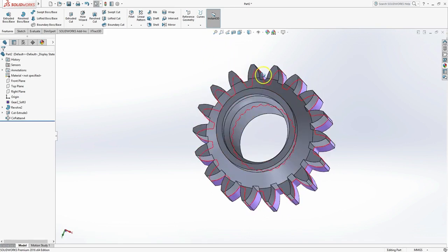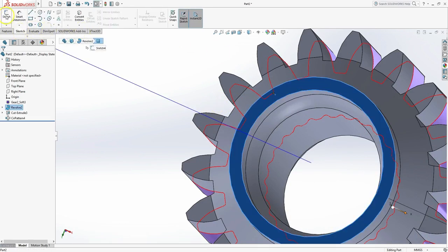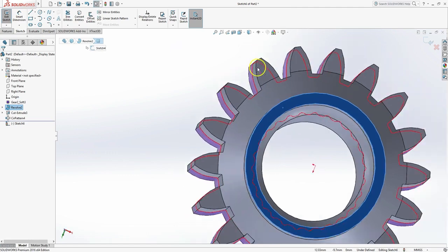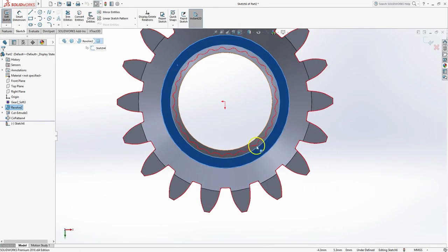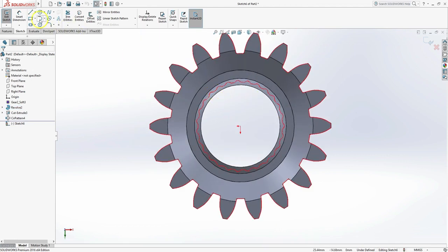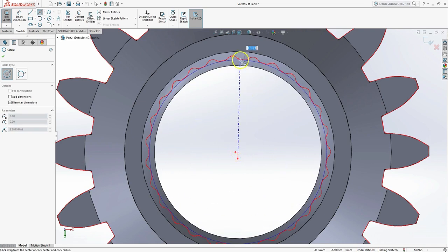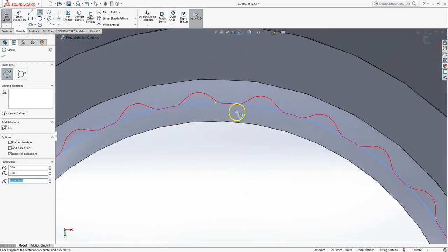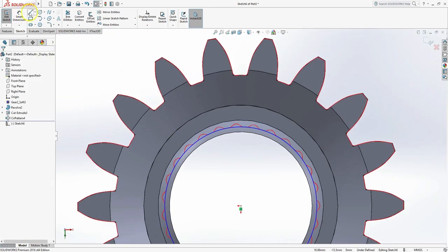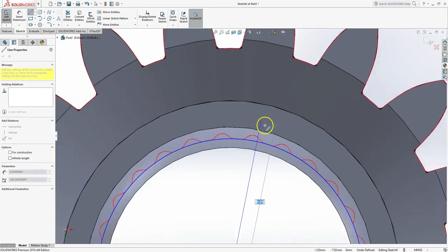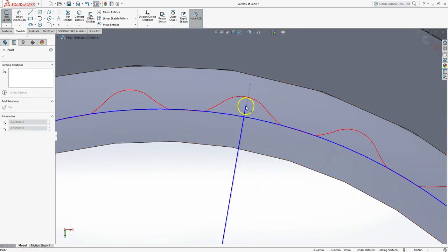And now I'm going to do the exact same thing for the inside, and I'll use this exact same sketch plane. I'll sketch right on top of that. Get that a little bit closer there. And I'm going to use the same process I used before. I start by creating an axis there to define this circular portion right there. Draw a center line on one of these teeth. Doesn't really matter. We're cutting out material right there. Put it right about there.